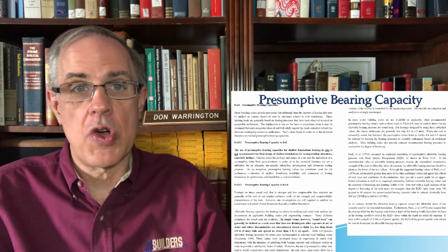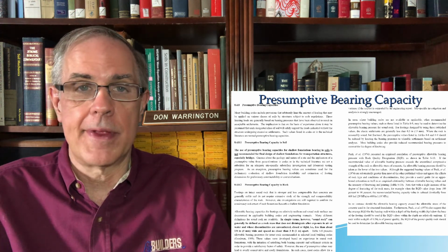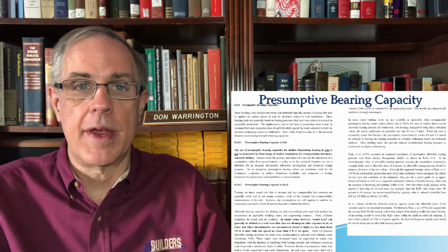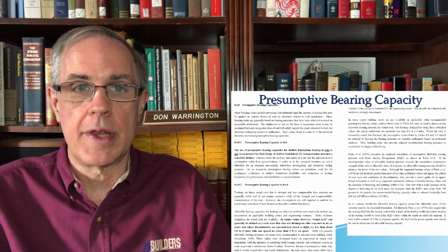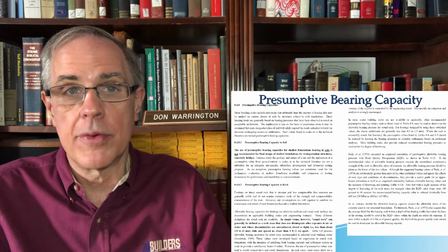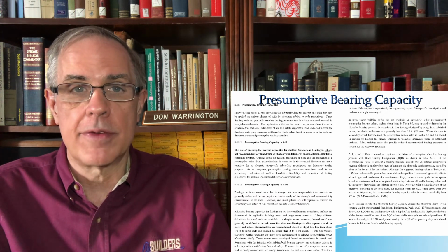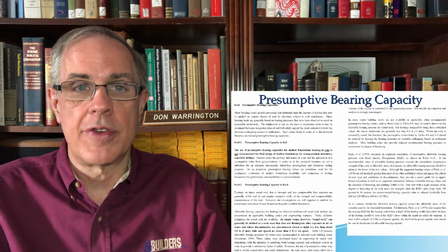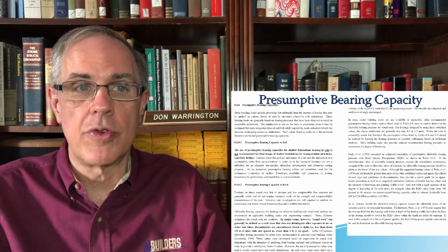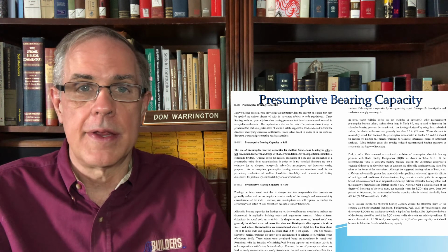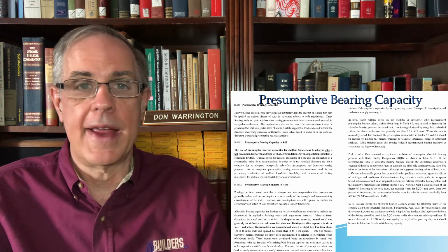Many codes, New York's is a good example, are based on that. In other words, traditionally they have given you a limit as to what your bearing capacity is. You take that, and if it's an eccentric load, you simply reduce it using Meyerhof's method, and then you live happily. You just apply it, and that's it.